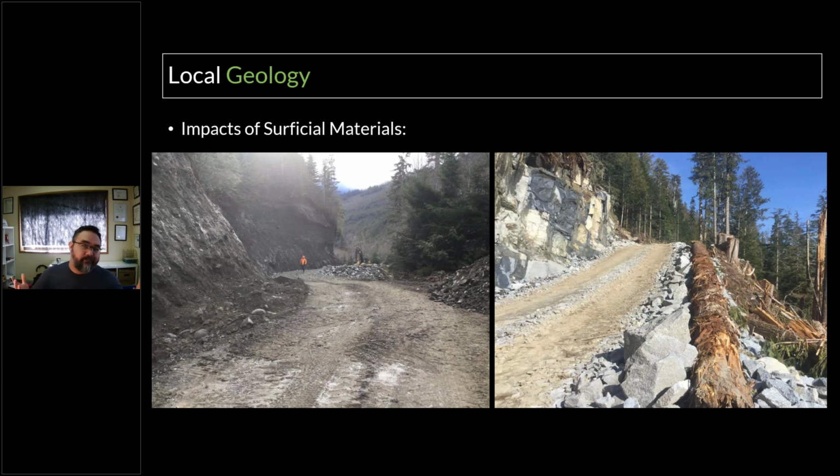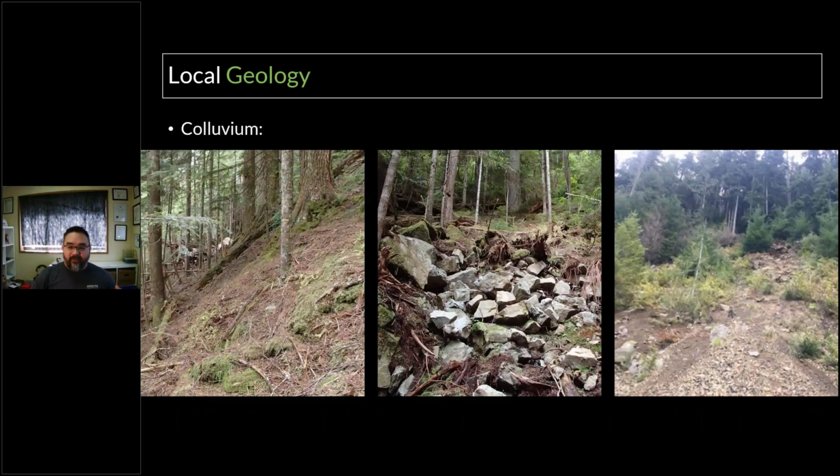A significant part of my practice is going to these roads where there's problems, and a lot of times it's just dealing with the spoil sites. For a few of our clients, we have to do detailed design of spoil sites with slope modeling to make sure that the spoil site is stable. If you don't understand your land base and the geology, you might not know what you're going to hit as you go ahead.